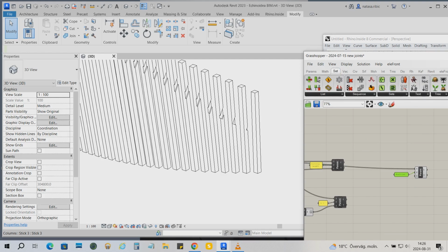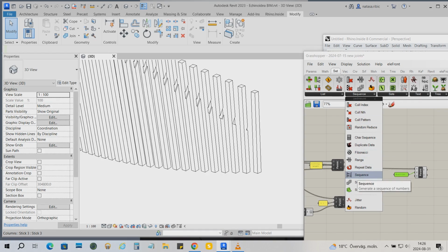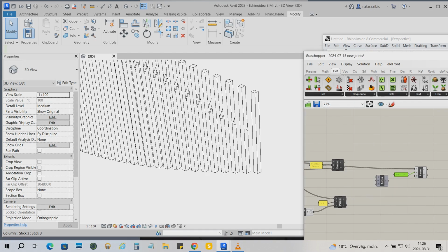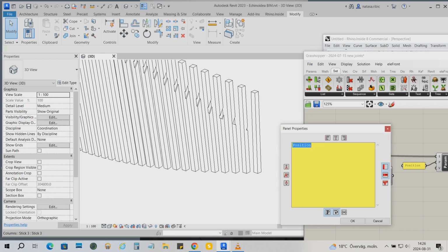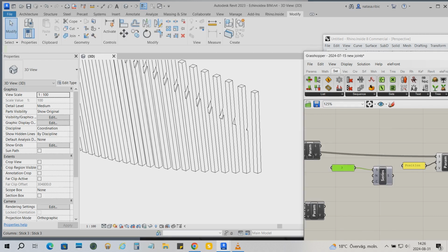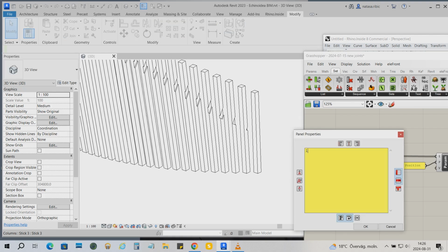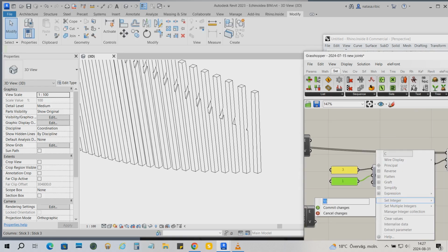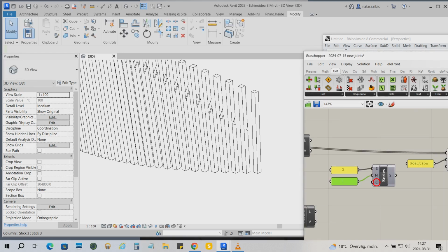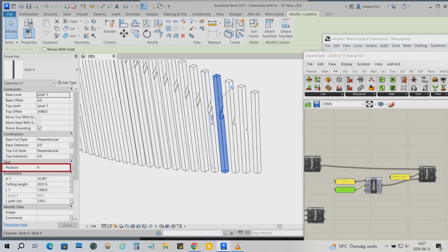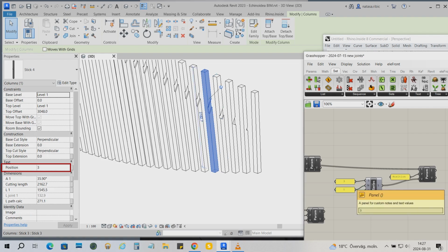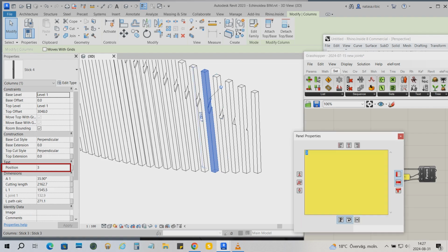The name is correct, the position is correct, and now we will use series component, and here we will start with the position 3 and we will increase the number with 1. And we have only 2 sticks here, so I can right click and write 2. And let's see, the position of this stick is 4 and the position of this stick is 3.